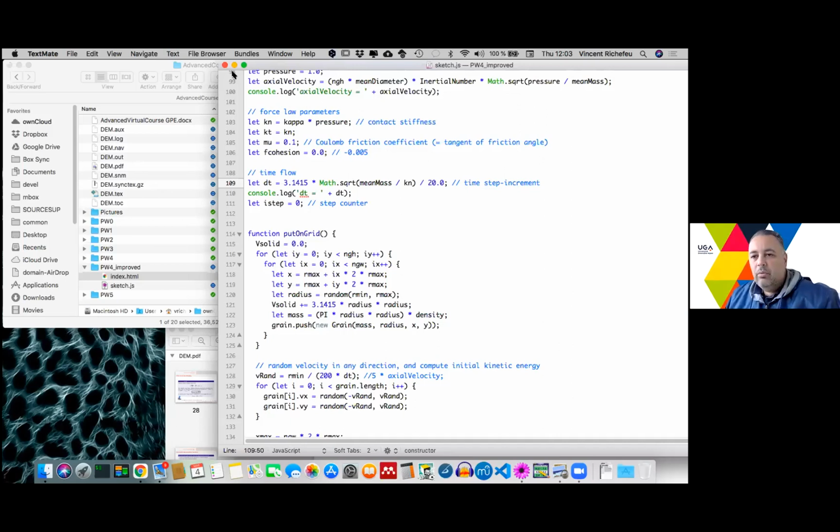Maybe you think that there are some DEM modeling where we can change, for instance, the size of the particle. Size, yes, expansion, or chemical strain. For example, particles that change their shape a lot. Okay. Can be. You can do that. When we make a rigid assumption, the model is written like this. But even if you've got a rigid assumption, you can change the shape.